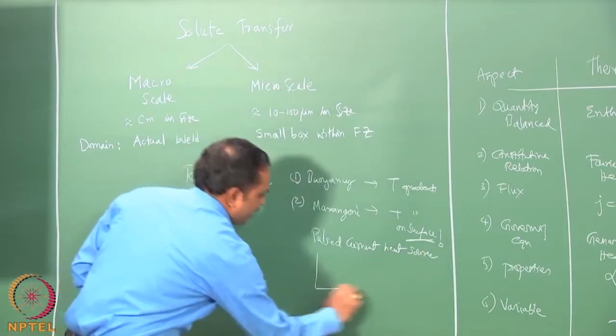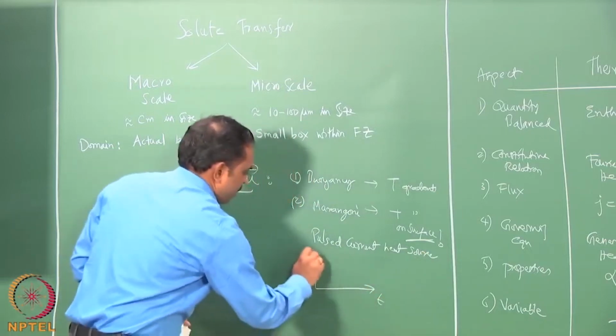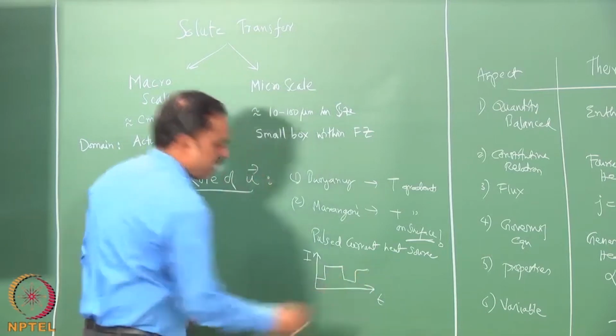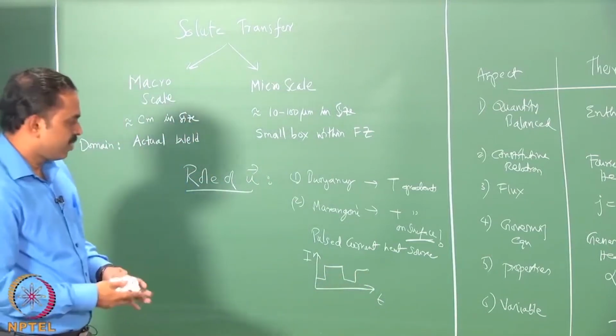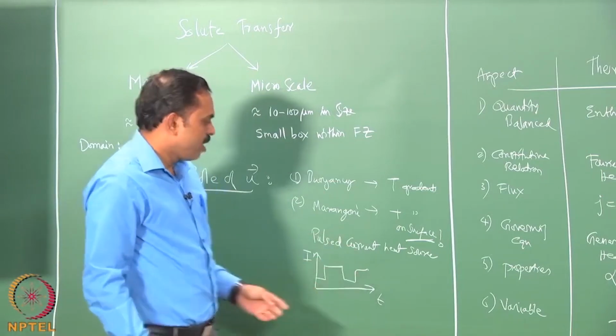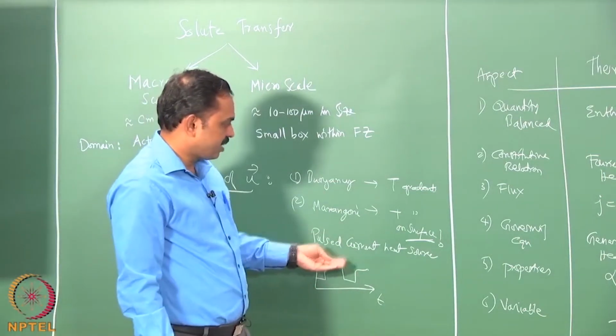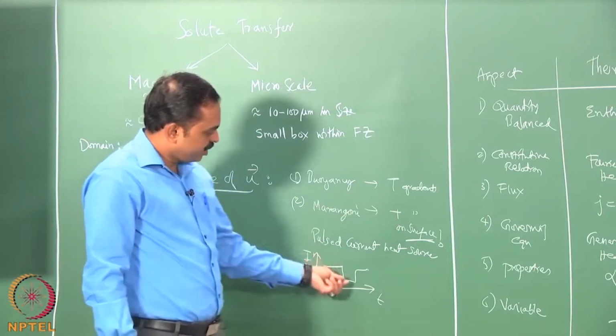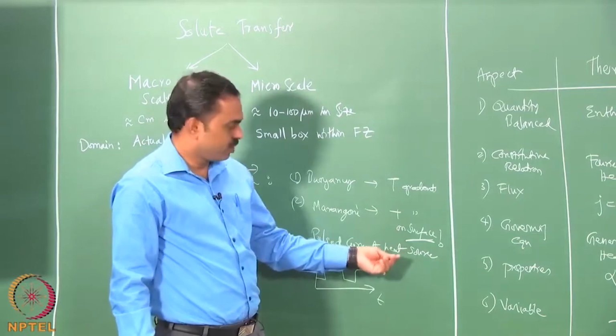What it implies is that as a function of time, the current is going to be taking shapes like that, and it means that for some duration the current is high and some duration it is low. So, in the durations where the current is high, the maximum temperature achieved will be high, and in the duration when the current is low, the maximum temperature will be low.